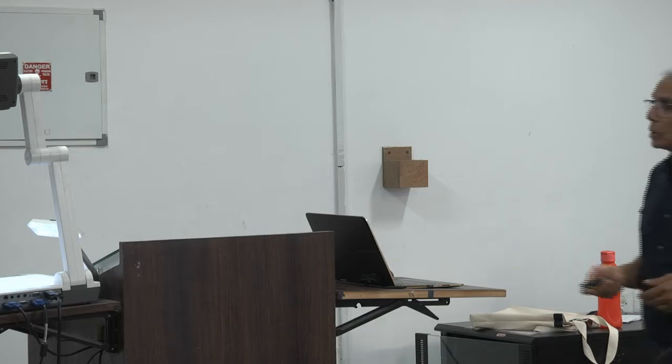So we design more on the safe side, so the engine can become heavier. Whenever we say heavier design, over-design, we mean thicker. So the part is this thick. If you're having a problem, just increase the thickness of the part, the gauge thickness. So the same loads would be applied on a bigger thickness, so the stress will be down. Yeah? So that's over-design. That's how you overcome under-design, by over-designing it.